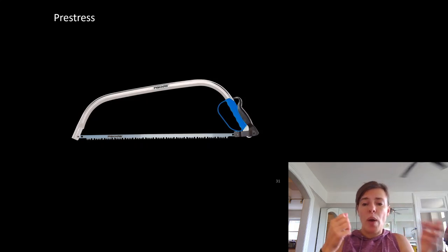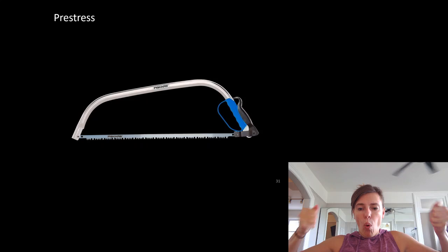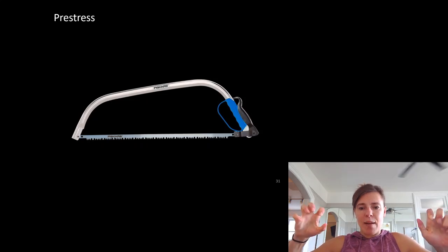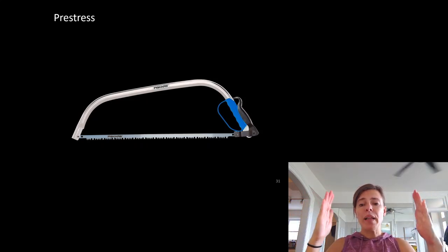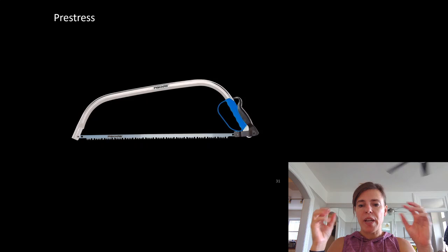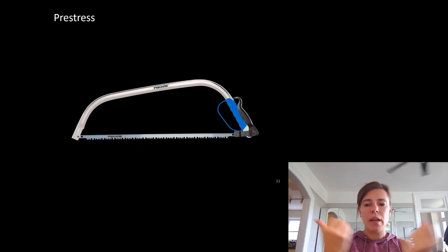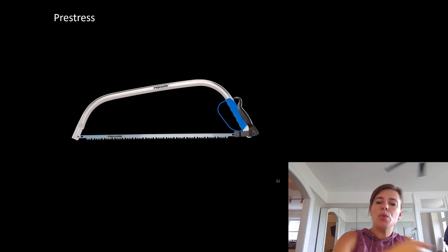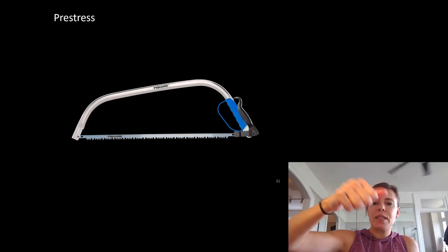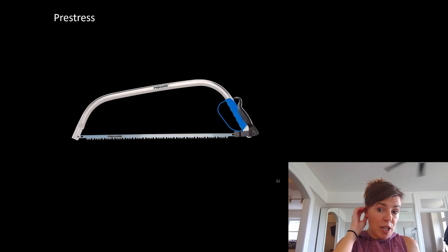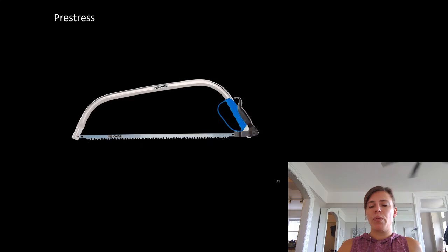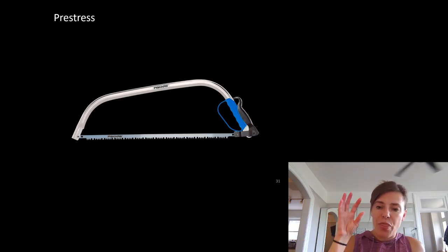Pre-stress is when we tighten something and hold that in place in some way so that when we apply a load, we're not trying to squash it, we're actually unloading the pre-stress. Anyone who's used a saw knows that unless you have that handle clamped, that blade will just buckle, and what you're doing there is pre-stressing it. Most of these ones are beyond the scope of the class. I just want to point out that they're all things that we do think about. Sometimes we think about them and say, okay, that's not a problem, but we have thought about it.